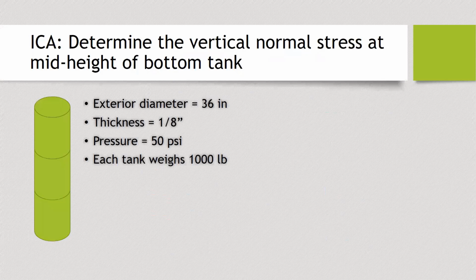What I want you to see here is the idea that now we could actually have different forces causing stress components in the same direction. Because in the two problems that we've done so far, we have different forces acting, but each of them creates a force in a different direction. So either a different normal stress or only one created a shear stress. We never really had to superimpose them. Instead, we just overlaid them on one cube, but never had to add numbers together.